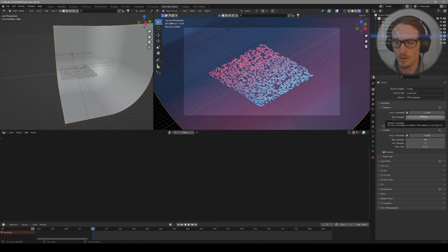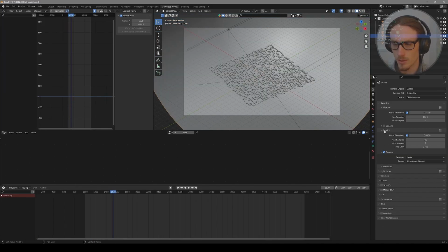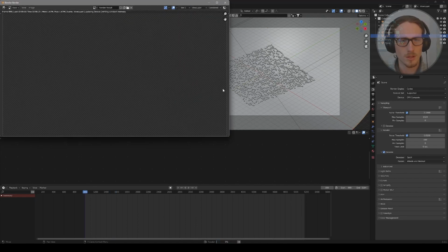Now you're almost ready to set your final render. You just want to go change your sampling for your final render. Something like 400 might be suitable. And I choose denoise and I have OptiX selected using my graphics card. So you can see my render, max samples, only 400. And then I can go up to render and render animation.